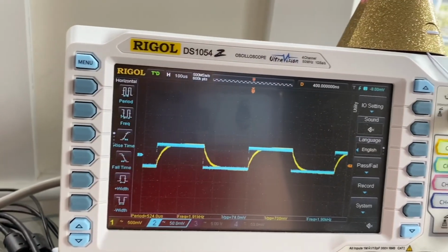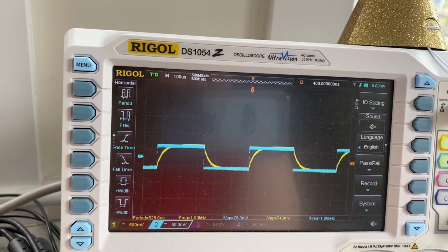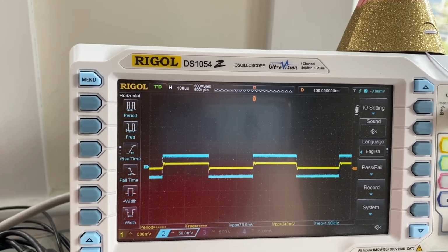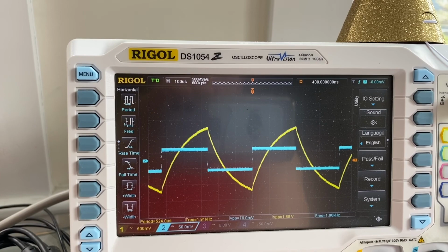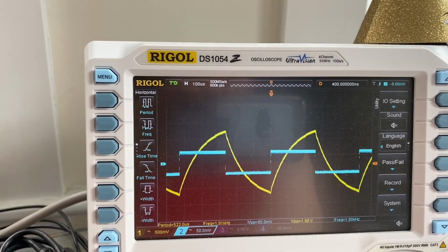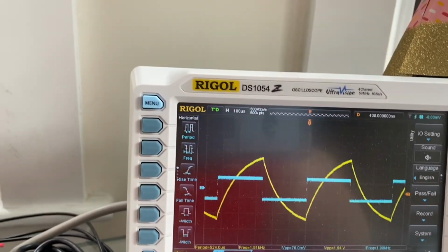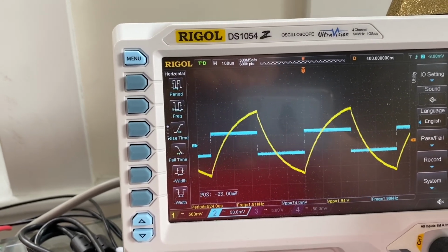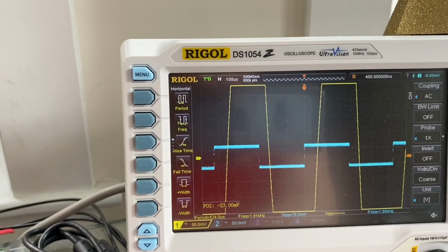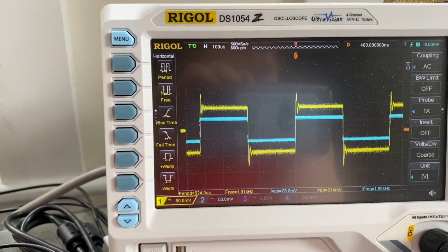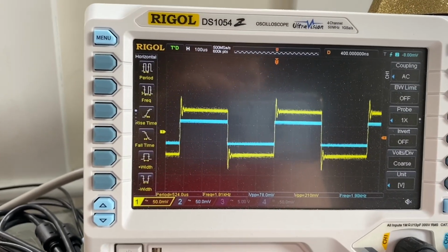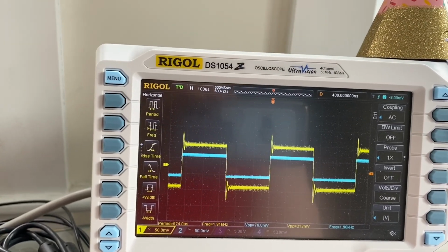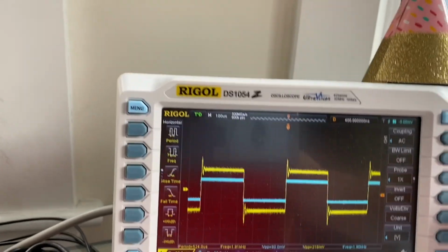So now if a gain of 10 happens, we see we're attenuating too much and we actually have trouble reaching that slope. So here's increasing the gain, and the big capacitor relative to the gain is making us really slow down a little bit. So let me get to channel 1 and move it down, and we see here's with the compensation capacitor versus without. Absolutely way better.